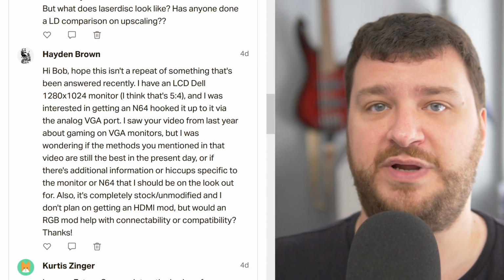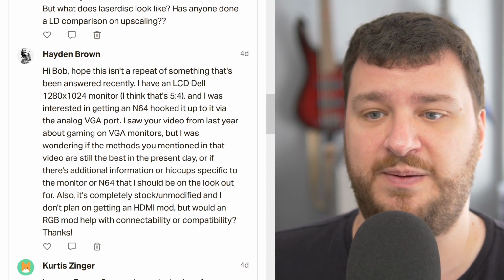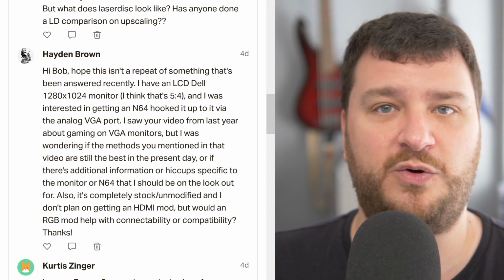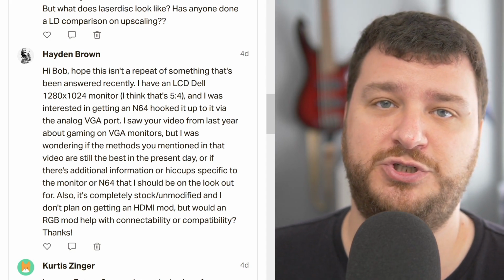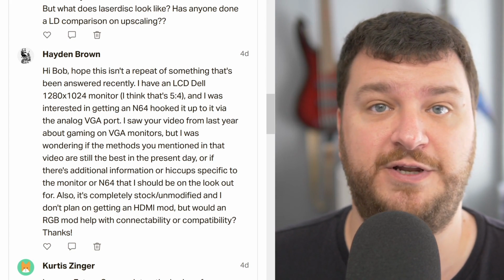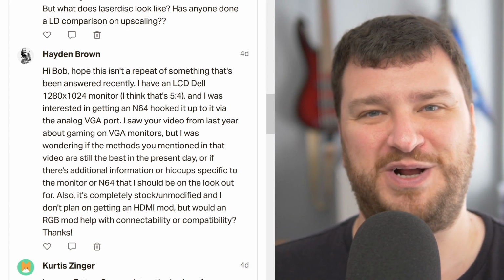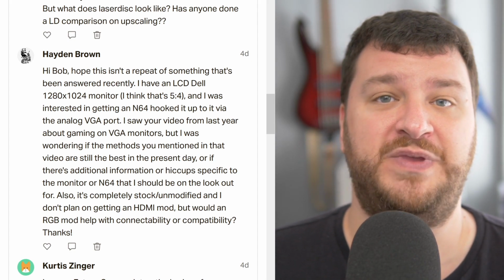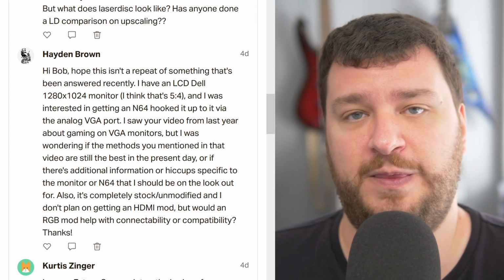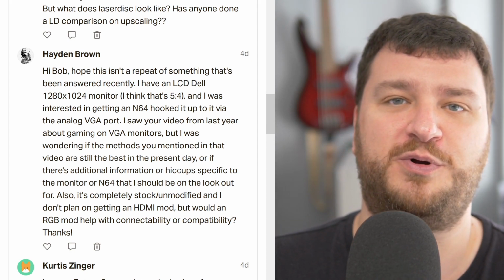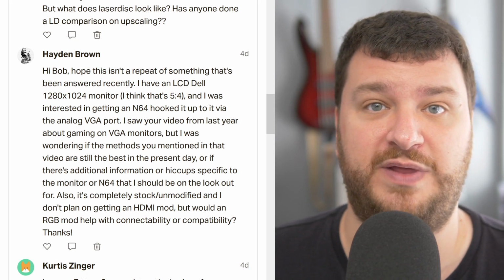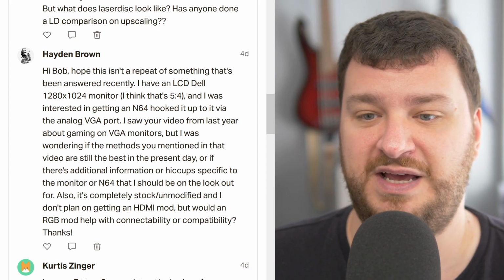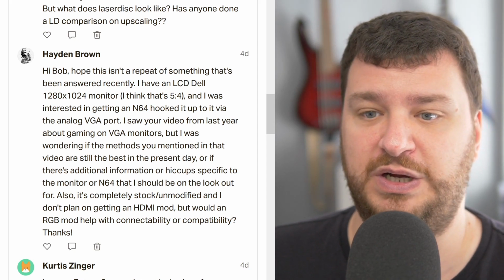Depending on how far you go dialing in signals and how you want to set it up, it could look equal to a PVM or not quite as good, maybe like a lower end or beat up PVM, but still sharper than a consumer grade TV with composite video would be. I always have to bring up the point that I think composite into a consumer CRT or even an RGB monitor is awesome and a great solution. But if you're chasing the sharper picture, that's definitely a way to do that, by using a VGA CRT monitor you could find on the side of the road sometimes. As long as the tube isn't too dim, you're good to go.